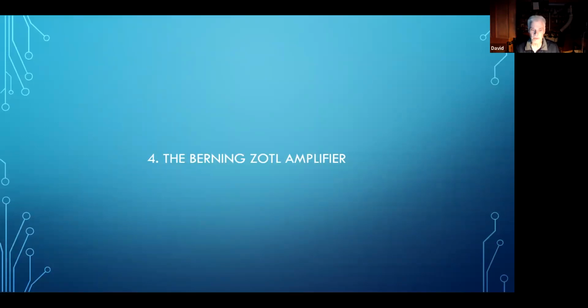I was trying to make this work, and I actually did make it work, but it wasn't working in an acceptable way. There were little glitches on the waveform, which you had to look closely on an oscilloscope to see, but you could hear them quite easily. There were little buzzy things, and they were the result of diode recovery. And I came to the conclusion that this isn't going to work.